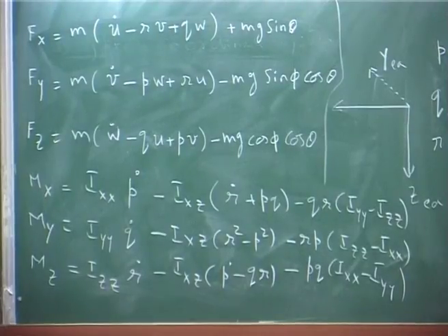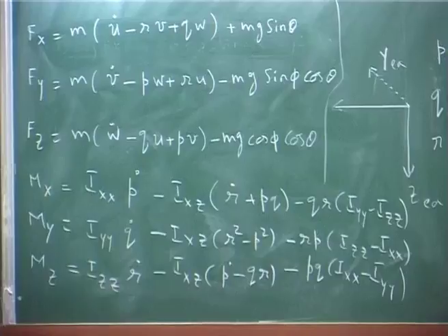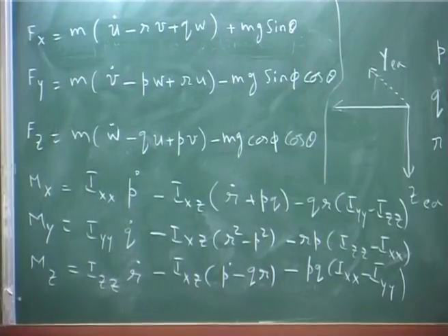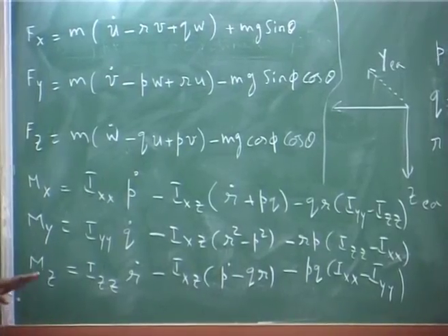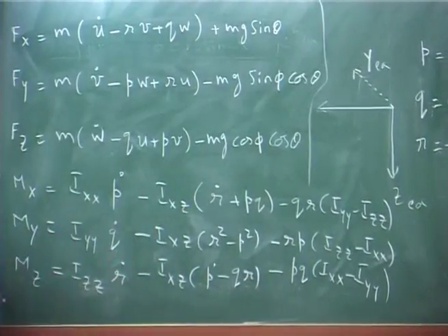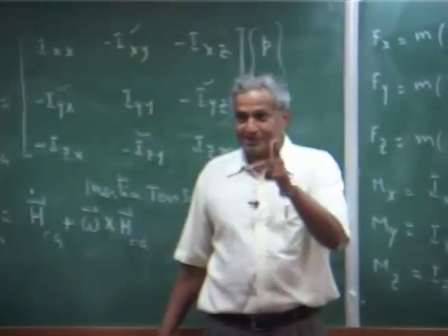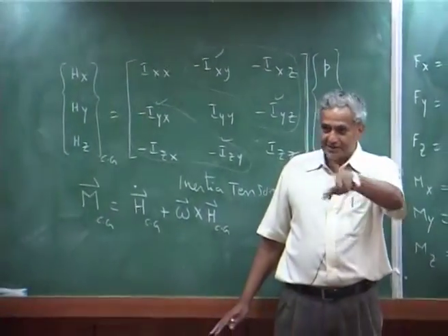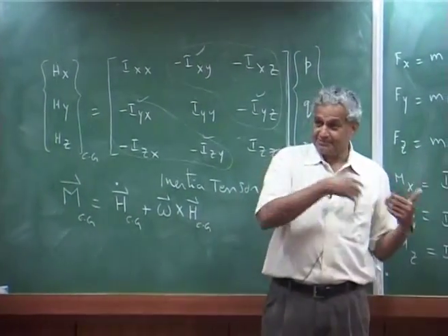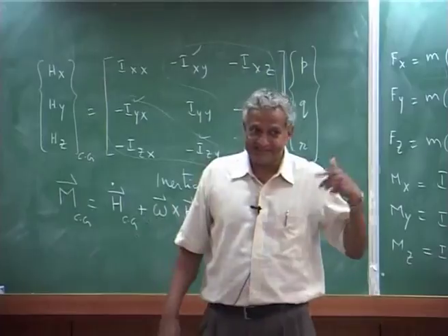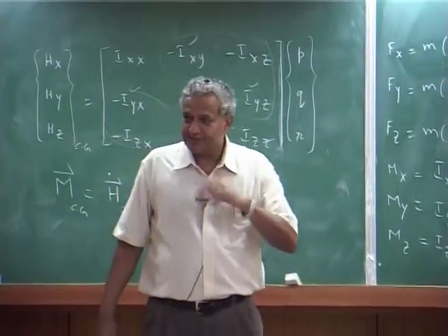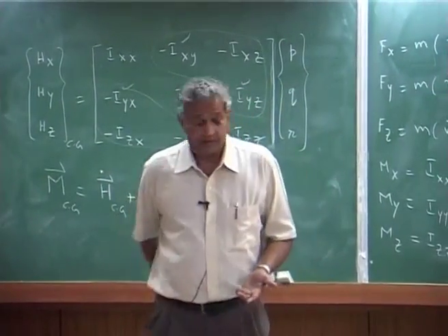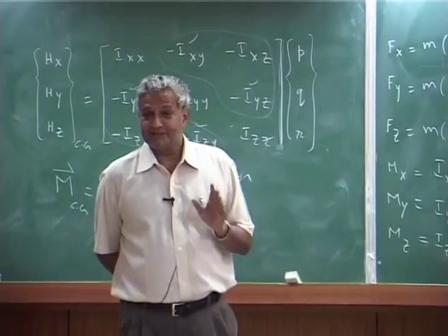You make an estimate from the drawing and then you calculate the complete Ixx, Iyy, Izz, all these numbers for a given coordinate system, because if you make a mistake there, your flight dynamics is all wrong. So, sometimes it is a routine job, but one has to do it in an aircraft industry.